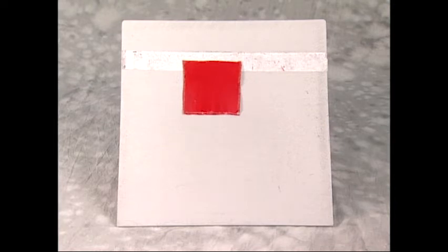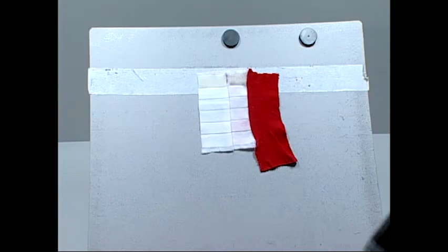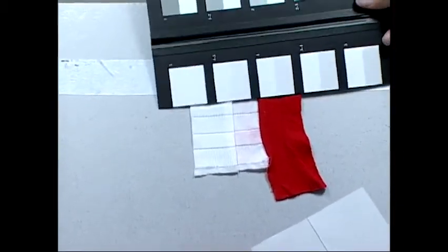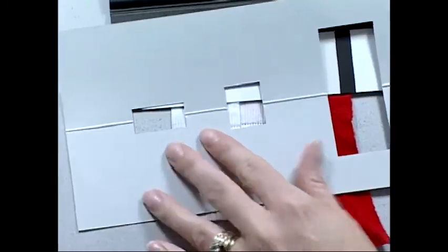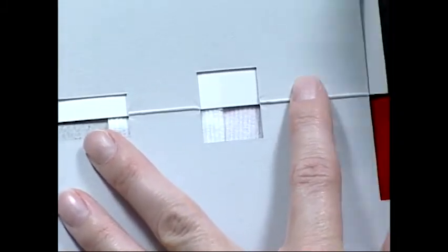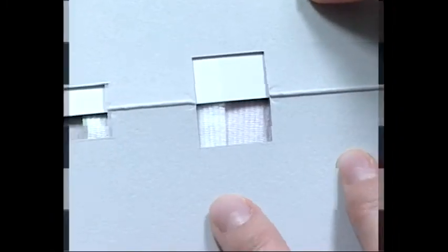The surfaces are illuminated with a daylight simulator at a standardized illumination level. The visual differences between the original unstained and stained pieces are compared with the differences represented by the grayscale. The grade of the specimen is that number of the grayscale which most closely corresponds to the contrast between the original and the tested pieces.